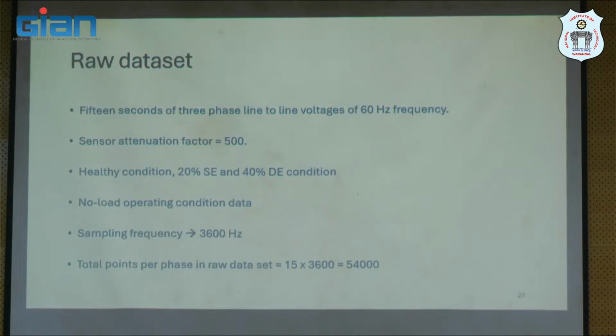I collected this data for 3 different operating conditions and used them for training. I will talk about training in a moment. The 3 conditions were: the induction motor with no eccentricity, 20% static eccentricity, and 40% dynamic eccentricity. It's not a mixed eccentric fault, just individual faults. In all these 3 scenarios, healthy, static or dynamic eccentric, the induction motor was operated at no load. That means there was no load coupled to the shaft.